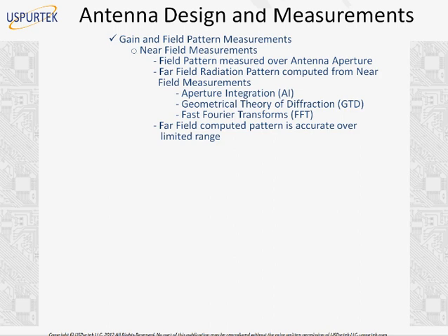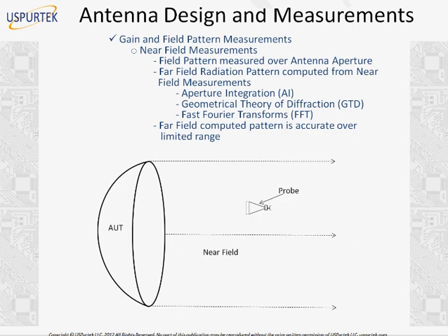Now, next topic is the near field measurements. These can also be important because they are required in certain applications where you have to mount your antenna with other equipment nearby. So you need to know what the near field looks like, so it doesn't interfere with any other equipment which is mounted around it.